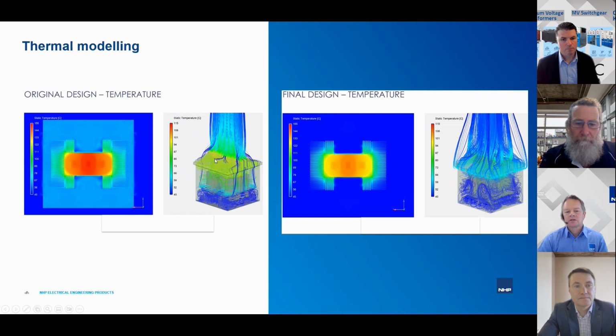And the temperature of the air within the enclosure around the roof space is high. It moves itself down, and it's moved down enough you can actually see venting out of the lower inlet vents. And the last thing you want is to have air coming in and out of the same spot. So we know we've got issues if we still have that. And we also know that the high air temperature around the transformer is not going to do the transformer any help at all.